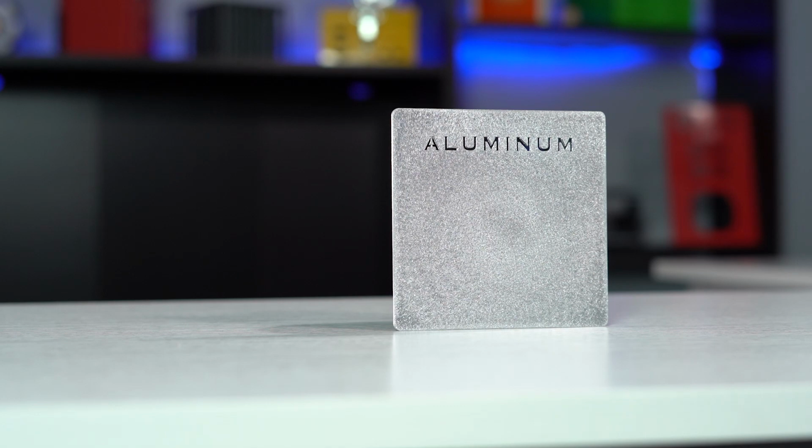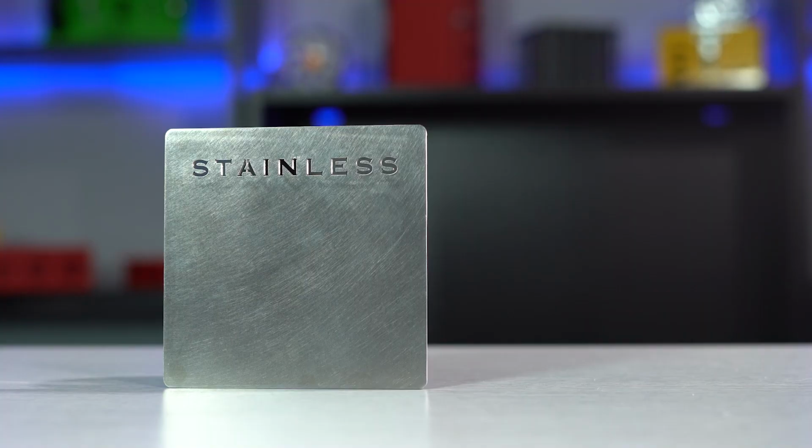Aluminum is corrosion resistant and lightweight. It does have a low structural stiffness, about 1/3, which must be compensated for by thicker gauge. Next material is galvanneal. Galvanneal is significantly more durable in wet environments, but it's not as durable as stainless or aluminum. And finally, we have stainless steel. Stainless steel is your best bet for corrosion resistance and has the same stiffness advantage of steel, yet even a higher strength.